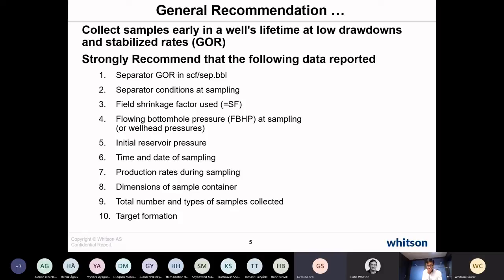We noticed in some of the wells, in some deep gas wells, that we have to keep on circulating MEG or glycol, and operationally we just can't disconnect the glycol or the MEG injection because we are afraid of the hydrates during well testing.